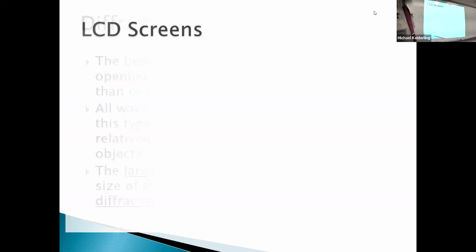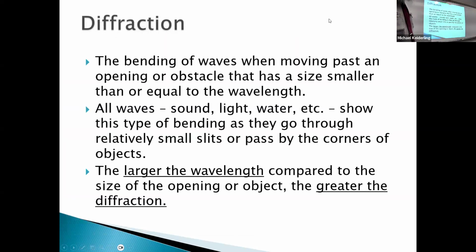And modern LCDs don't go from 0 to 90 degrees like they've shown in there. They go from 180 to 270, I think. They do more twists because it turns out you can make the change more efficiently that way, needing less electricity and saving you power.